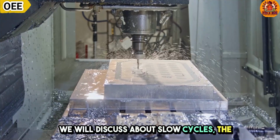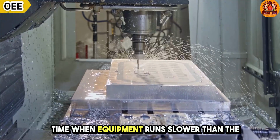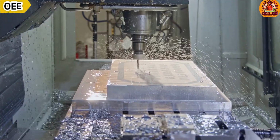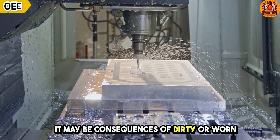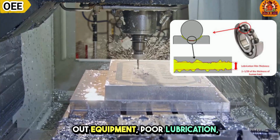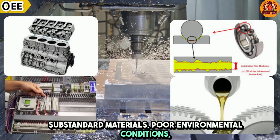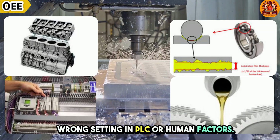Then slow cycles is the second form of loss in the performance category. We'll discuss slow cycles. This is the time when equipment runs slower than the specified cycle time per component. It may be a consequence of dirty or worn out equipment, poor lubrication, substandard materials, poor environmental conditions, wrong settings in the PLC, or human factors.